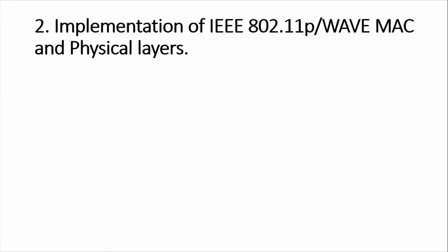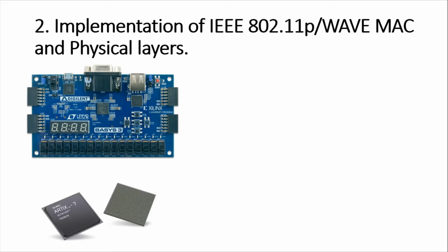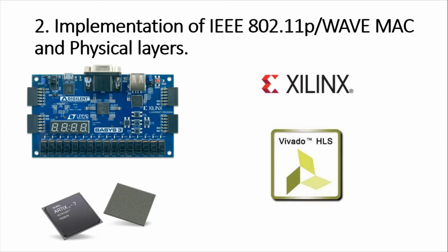The hardware implementation is done on a Basys 3 FPGA development board. It has a mid-range Xilinx Artix-7 FPGA chip. Xilinx Vivado High-Level Synthesis is used as the implementation technique.